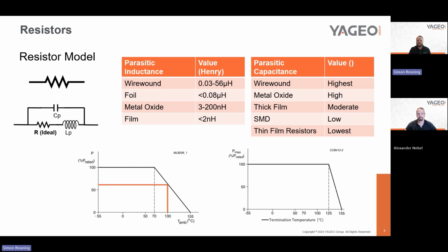And this is actually one of those errors. When that resistor fails, it might not always be a critical failure. It might just be that the resistance changes over time because it is run at a non-datasheet spec condition, and that will slowly damage the product. And that doesn't always mean that the product is just going to blow up, which is, in that case, of course, we know right away we made a mistake. But sometimes this is one of those errors where the part slowly is damaged, and we may not know right away that there is an error until you see, hey, my product isn't functioning the way I intended. So what's going on? So make sure that when you start looking at power ratings for your resistors, that you do consider the operating temperature as well.